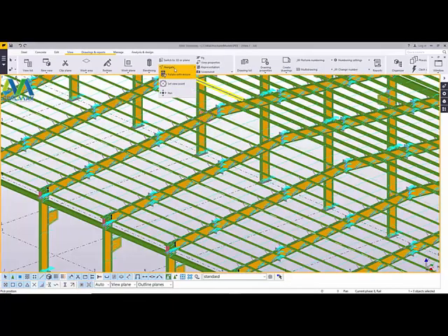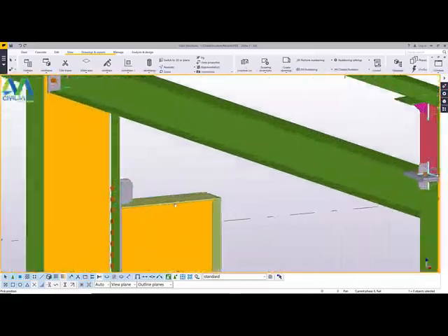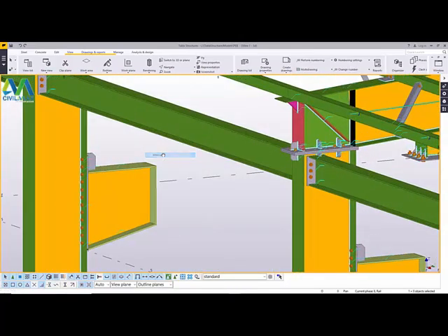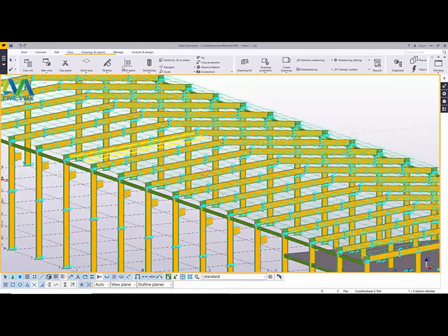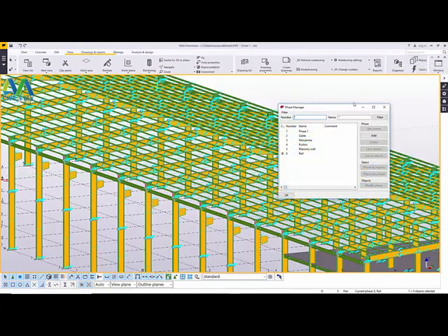And let me just come to the navigator, and I want to rotate this, and you can take a look inside. So we want to place the girders on top of these supports, rail supports here, and we can't work comfortably with all these obstructions in place. And to clear all this and make our visibility much clearer, we'll come to view here, and once you click on view, you'll get access to faces here, where you'll be able to click on this, then get to face manager.